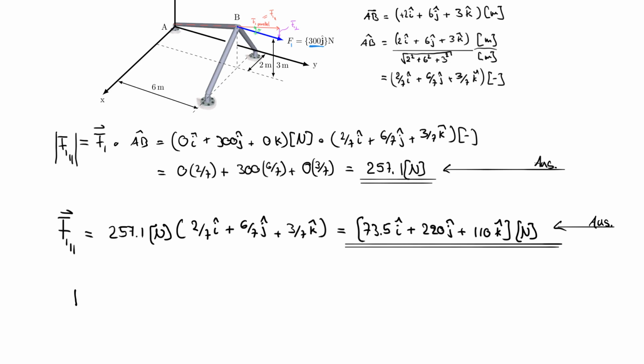So you could calculate F1 perpendicular, simply the magnitude of it by using the Pythagorean theorem, which would be F1 squared minus F1 parallel squared, and then the whole thing square rooted.